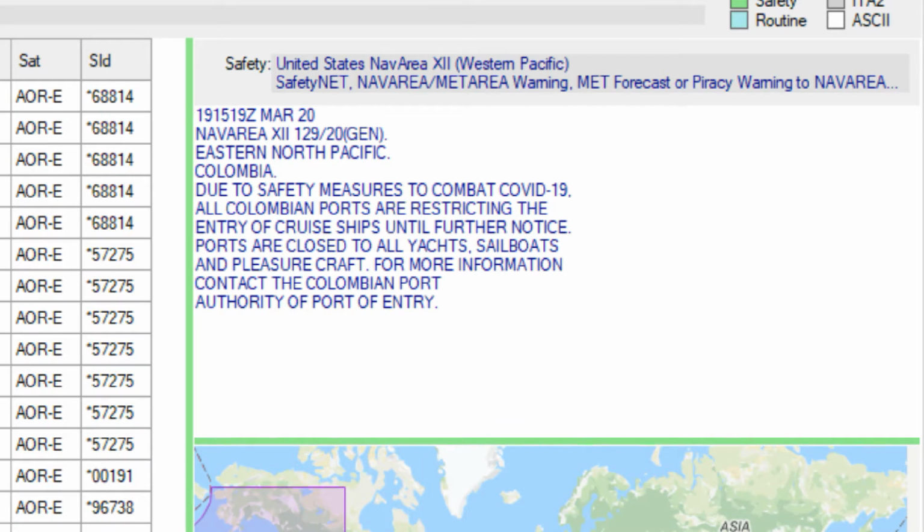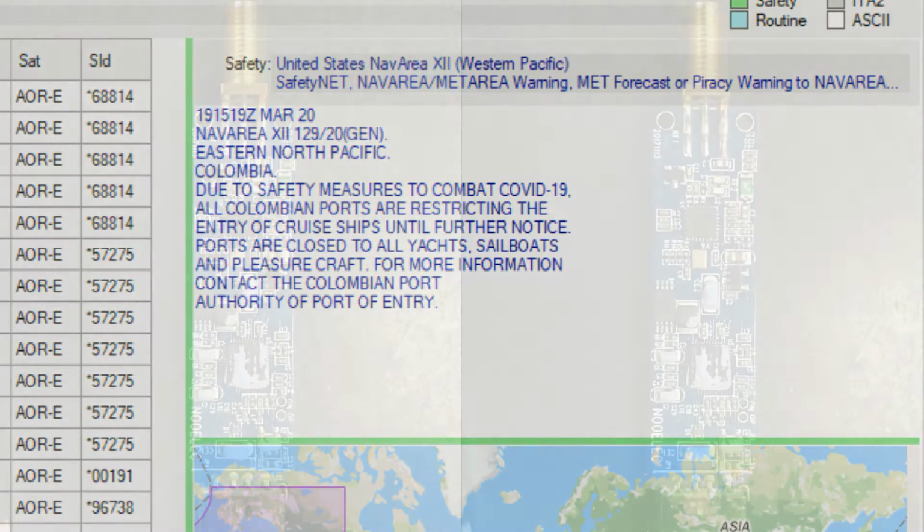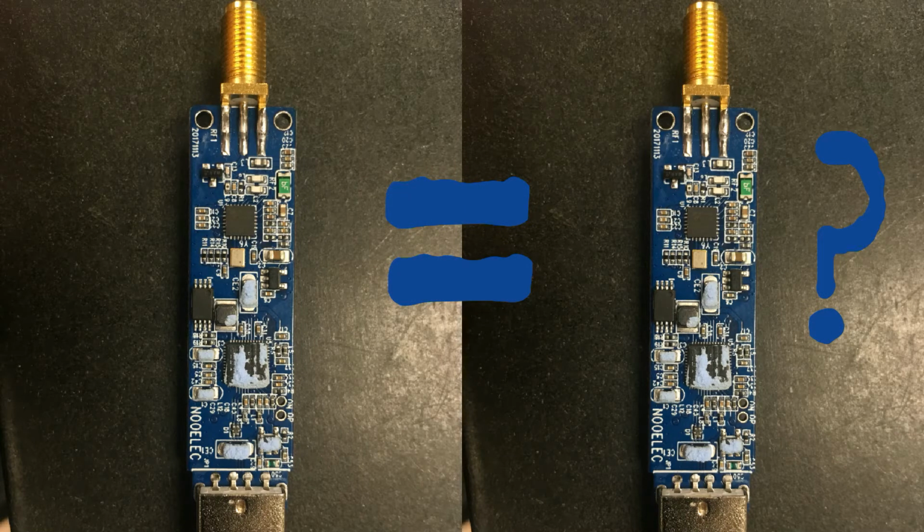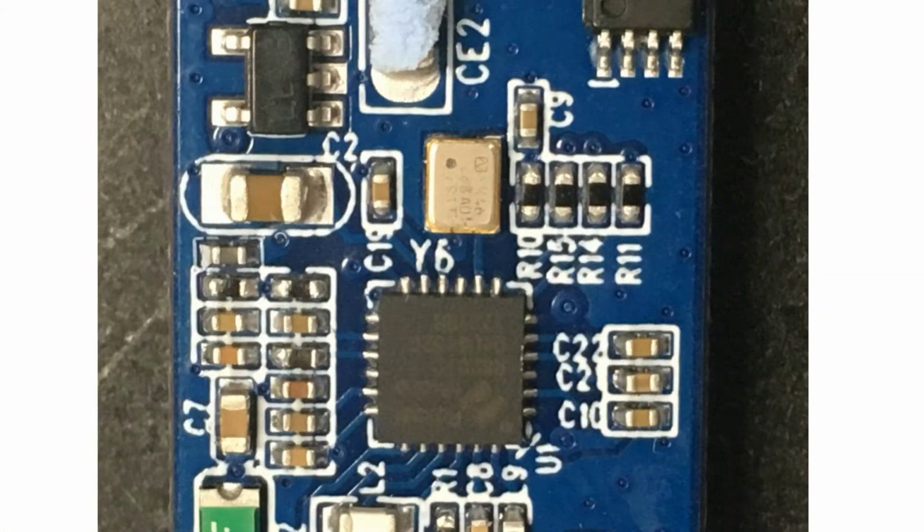Since we concluded that our RF front end was capable of receiving and decoding an Inmarsat signal, we could move forward with designing the array. One of the greatest challenges in creating a phased array system is synchronicity between the receivers. In order to accurately phase shift signals, the receivers must be sampling at the same time and not suffer from phase drifting. Our approach to this problem was the sharing of a clock.